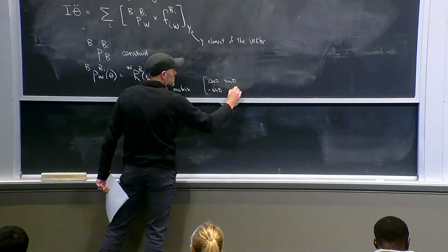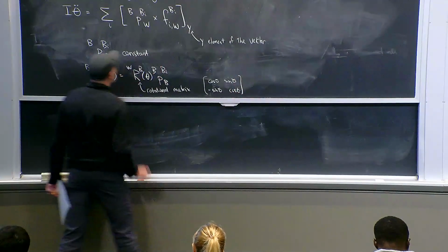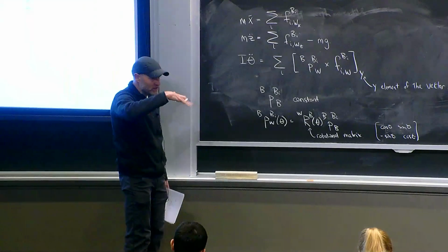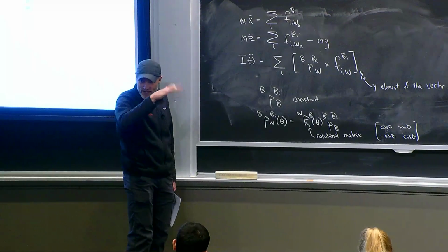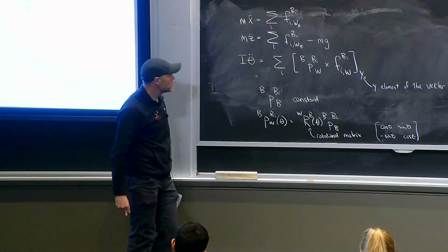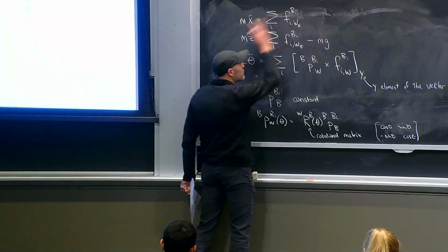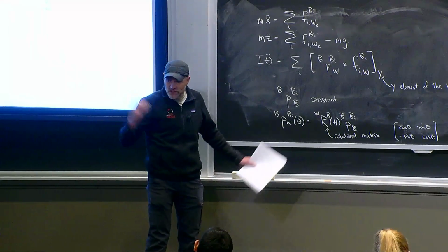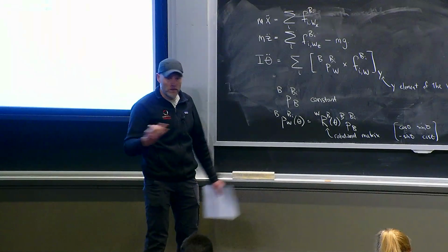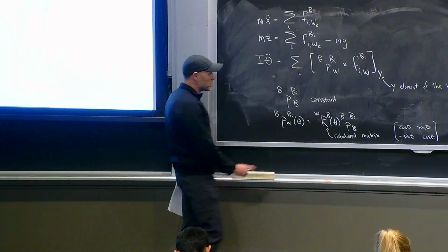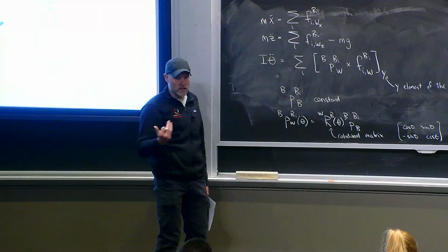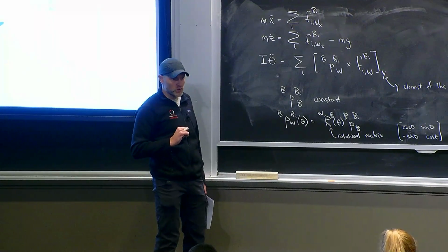So we have nonlinear dynamics there. If you kept the angle relatively flat, or you linearized around a small angle, then you could actually solve for trajectories of this system with linear MPC, linear trajectory optimization. You could do LQR. And if you start embracing larger turns, then we can just use your nonlinear control toolbox.